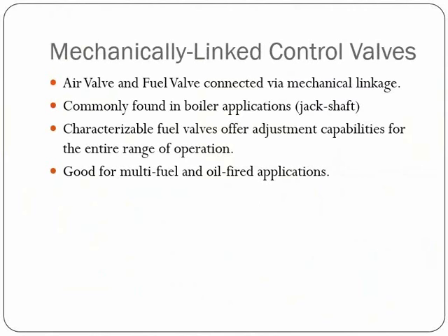With the mechanically linked valves, a lot of them have a screw carrier assembly at different index points between low fire and high fire. So this will allow you, to a certain degree of flexibility, give you a unique curve between low fire and high fire.